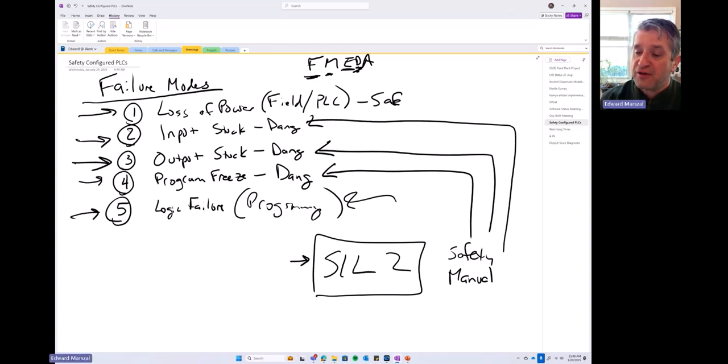Commercial off the shelf, you need to do that yourself. You buy a SIL 3 certified safety PLC, the equipment vendor has done all of that work for you. So do yourself a little bit of a cost benefit analysis to determine whether or not you want to roll it yourself or you just want to buy all this stuff directly from your equipment vendor.